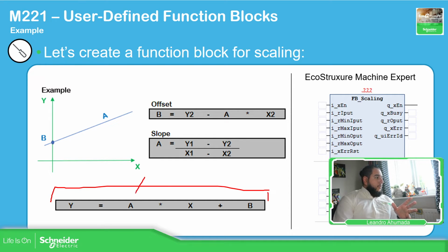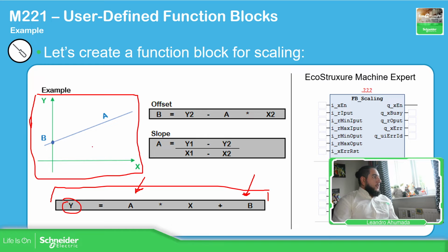So we already defined this value based on the configuration, and then we have the linearization. Now what I want is I'm going to enter the minimum and the max value for the input, and then I'm going to assign the minimum and max value for the output that I want, and then make the calculation on the PLC, and then having this result, okay, for the new input. So basically we are going to make a first grade equation here.